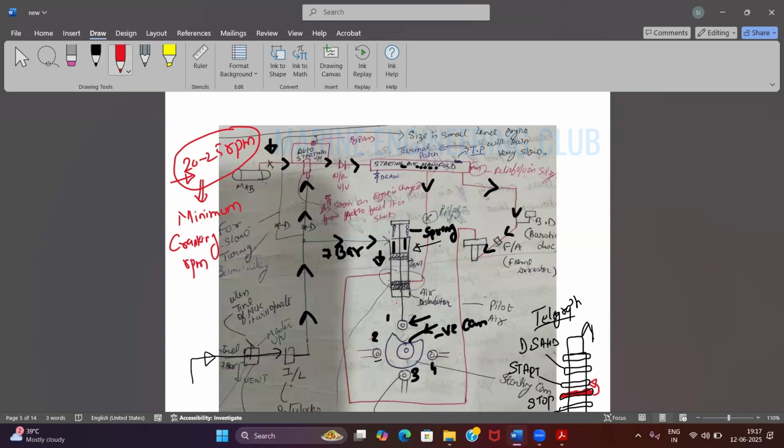At this point, when the roller comes down and the 7 bar pressure is acting, the top piston will block the vent. Agreed? And the bottom piston will move a little bit downward, opening up the channel for my 30 bar air to come. And only this particular unit will be getting air from the pilot air, and only number 1 unit will be injecting air into my cylinder.